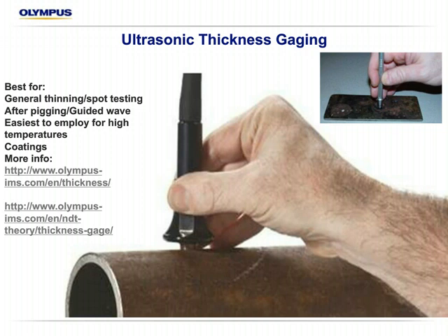It's obviously the easiest to employ for high temperatures, because we have specialized couplants and you can do a point, let it cool, go to another spot, take a measurement, which is much easier than doing a mapping where you have a scanner or a probe in immediate contact with the hot surface at all times. So definitely a very good application if you have high temp applications that you need to measure for corrosion.